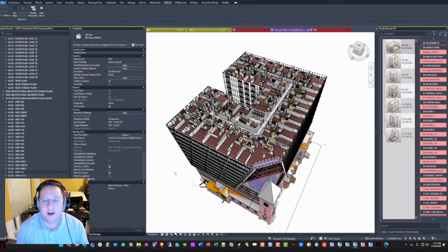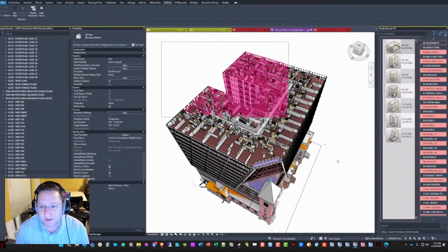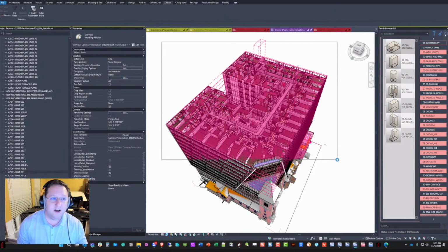It'll be fine. But what I wanted to show you is, if you work in multifamily specifically, but if you're working in Revit at all, the Juan Osborne tool called Filter More, the reason it changes your life is right there in multifamily. Have you used it at all? I haven't, but I use the pick tool in Revit, which is the same idea, right? It's a similar concept. Filter More actually can replace the Revit filter that shows up in the context ribbon.